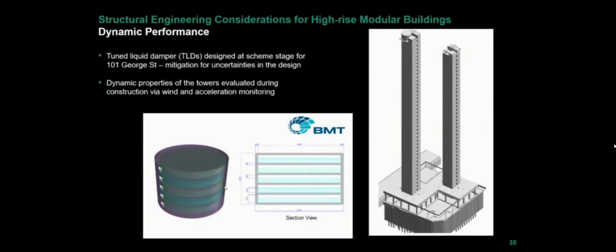So on George Street, because of our initial low assumptions on the module stiffness and damping, we did design a mass-tuned liquid damper with a company called BMT, who were in business at the time. So that was designed in based on our initial assumptions, and we had a position for it at the top of the core.